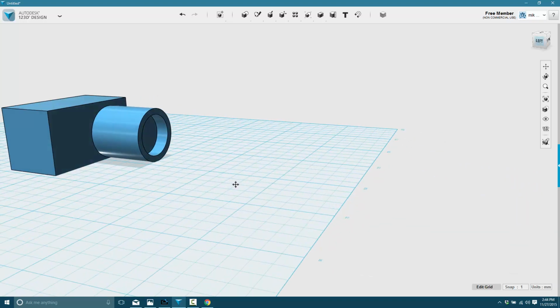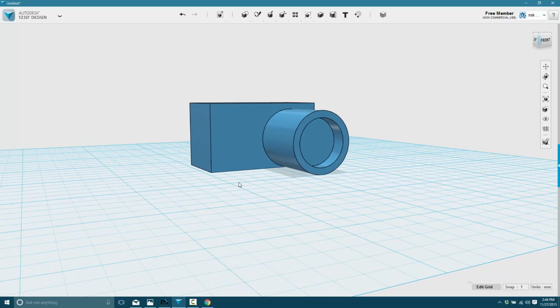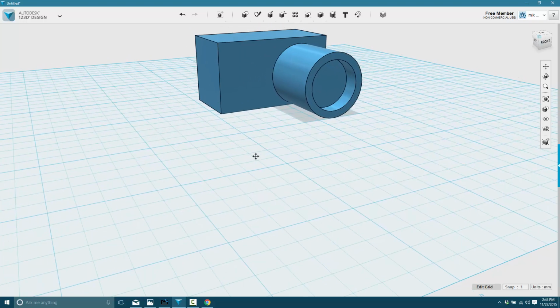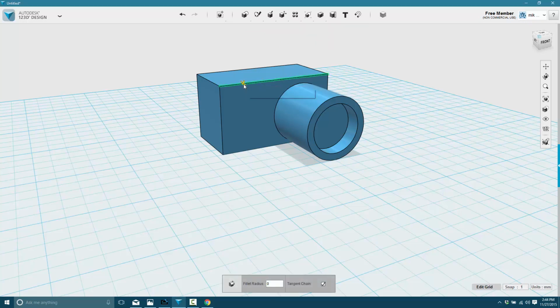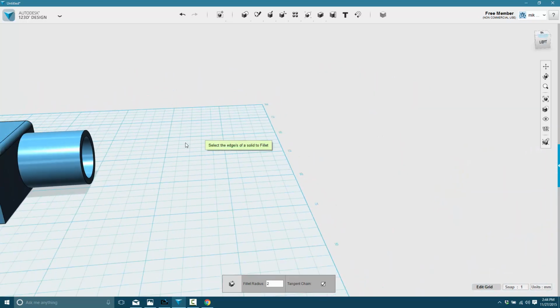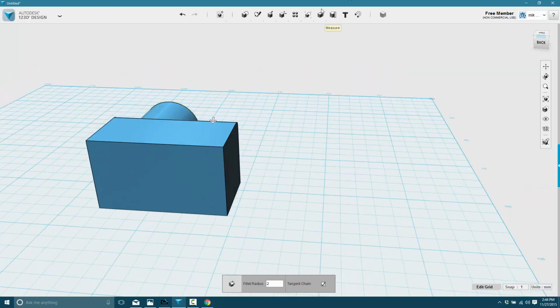And if you need to start doing things like, let's say we wanted to round this edge here, you can do that. We can come up here and do either a fillet for rounded or chamfer for beveled. So we'll do a fillet, pick our edge, and come on. So we can round that edge out slightly. As you notice how it's going to collide with this edge, it will deal with that automatically when it gets to it. So we could have also done a bevel instead.